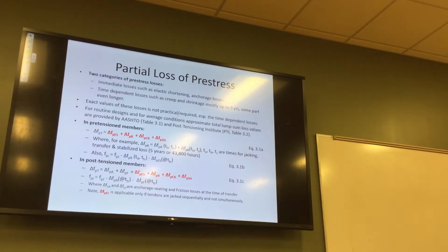Well, it's not only losing stress because of relaxation from beginning to end, it's also losing because of the other phenomena which we are going parallel, which is the shrinkage and the creep are also losing. Your pre-stress is lost. So the less the stress you have in your pre-stress steel, the less the relaxation, right? If you stretch something very hard, then it will tend to relax more. It's like creep. So what we are saying is, but the way we calculate is as if they are independent phenomena, you see. One doesn't affect the other.